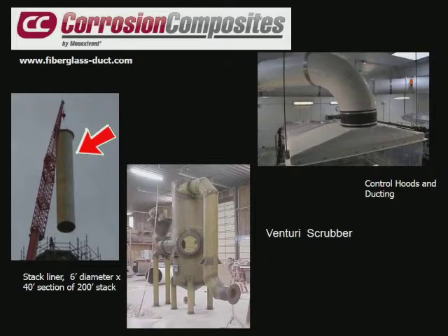So the sections dropped in place, and then the very last section on top only went halfway into the socket, and that flange that you see at the top of it sat on the concrete. This allowed for expansion and contraction, and with the system the way it was, it required no internal fiberglass joints. That stack, the first one, was installed in a 4-hour period, so we were quite amazed at that.